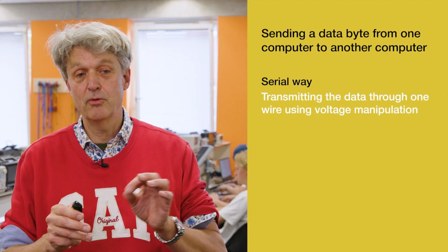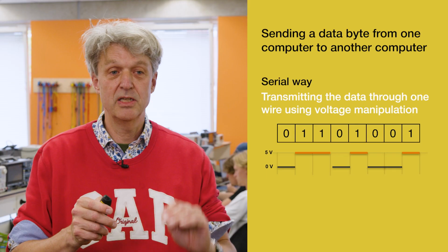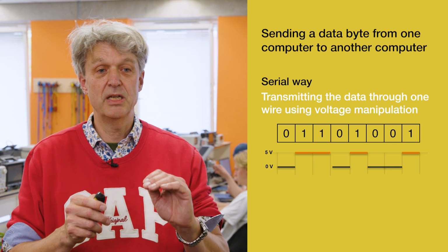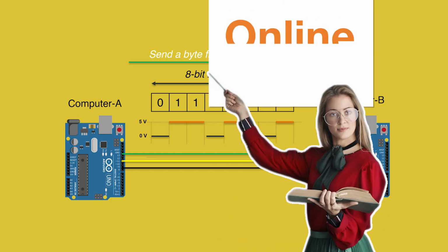That means you only have one single wire, and through this wire you're going to, using voltage manipulation again, transmit the zeros and ones. And you can clearly see over here, a 0 means 0 volts and a 1 means 5 volts. So if you take this sequence of zeros and ones from computer A to computer B, the second computer has received, after it received the individual bits, the entire byte at the other side.